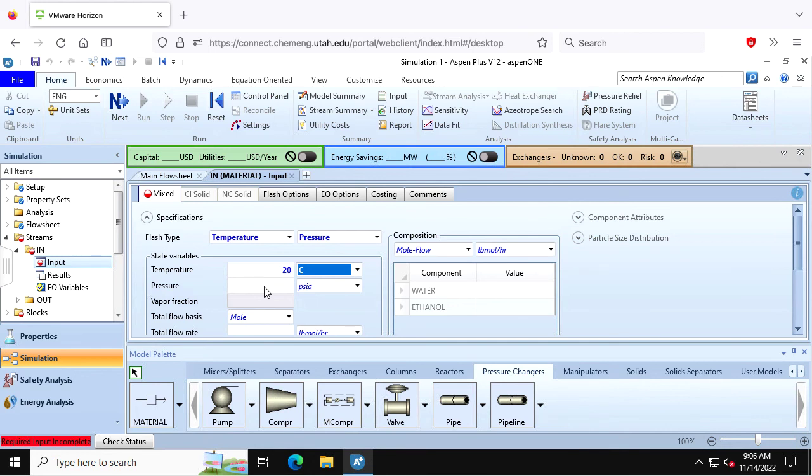And on the high side, it would be lower because it's the gas pressure on the top, and on the low side, so you'd have this pressure difference, and you'd say, oh, that's 6 inches. 6 inches of water pressure difference. And then you can calculate that out. But anyhow, that's why they use inches of water.